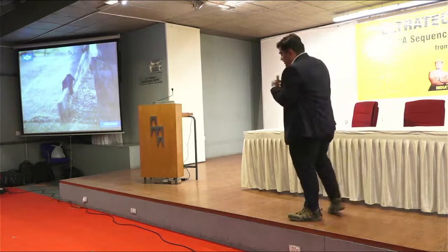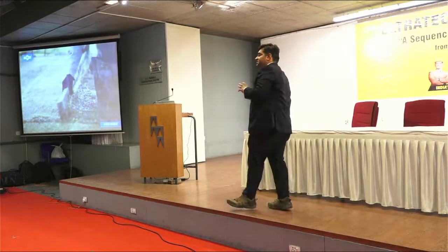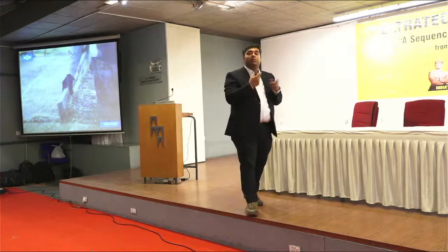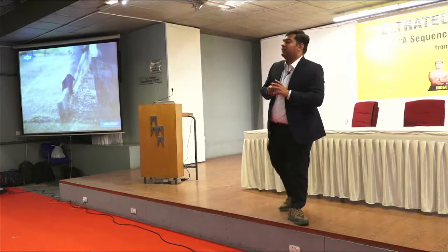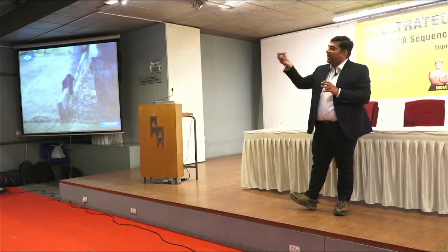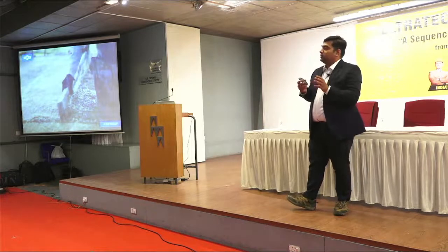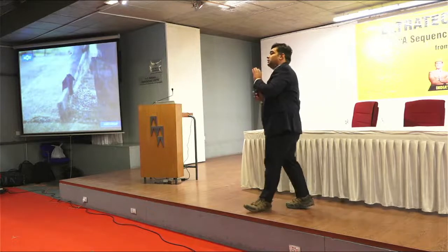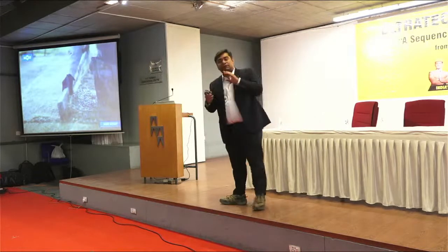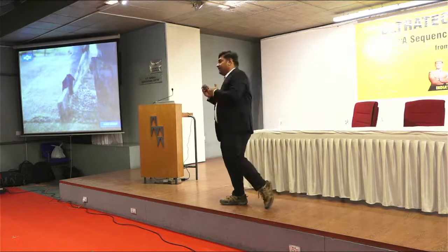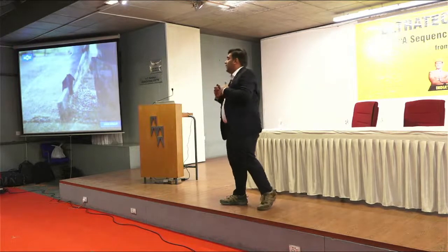And there is another thing which reflects the sustainability that concrete needs nowadays. It is the recycler plant. A recycler plant works like this: if some concrete is left in the transit mixer, it comes back to the plant. The leftover concrete is put in the recycler and water is flowed through. As the water flows, the aggregates and sand are separated. They are taken back as aggregates and sand and used again in concrete.